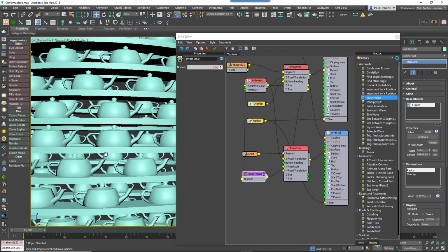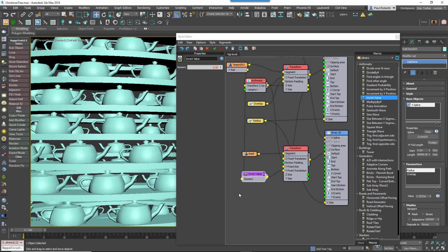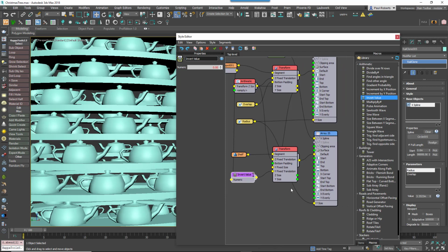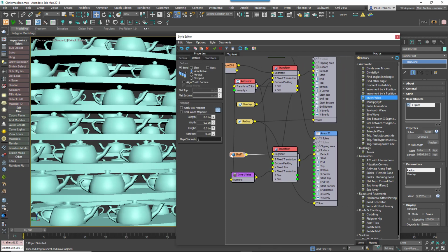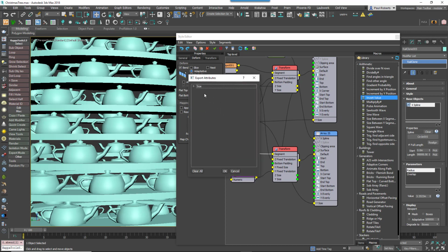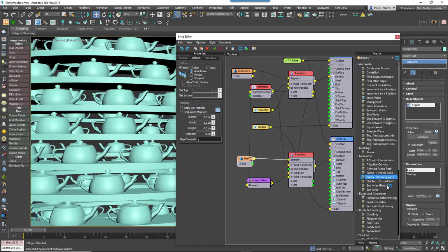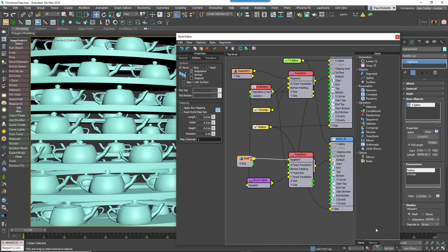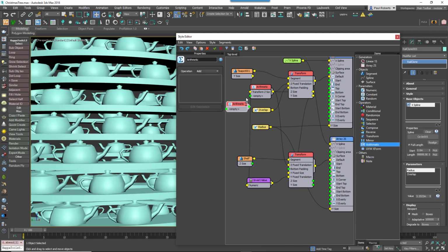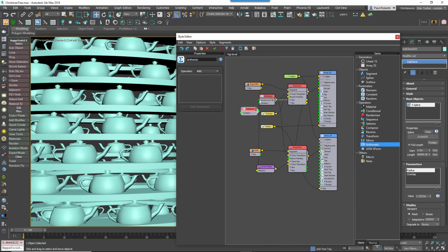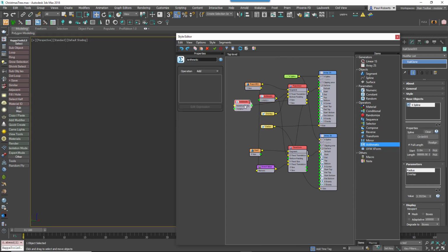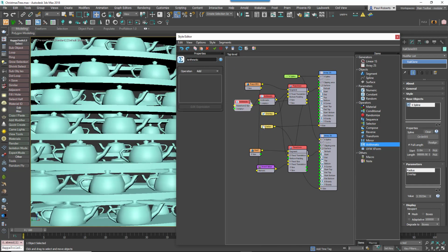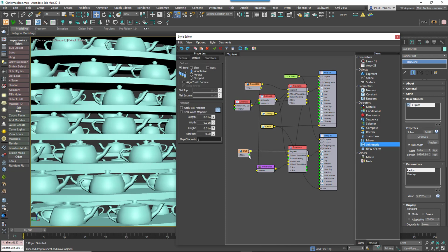Nearly there. All we need to do now is add the thickness of the shelf into the existing stepping expression. To do this, first export the Z size attribute of the shelf. Wire a new arithmetic node between the existing arithmetic node and the teapot's transform Z size property. Leave the mode set to addition. Wire the shelf's Z size property to the second input of the new arithmetic node. The size between each row is now the sum of the height of the teapot plus the shelf.